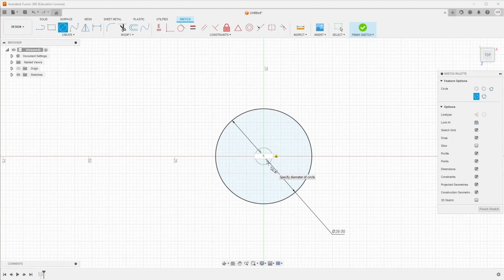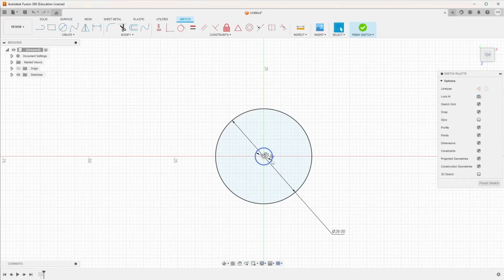Now, if you measured it and you were working in inches, you could type in something like 0.25 IN. And it will say, okay, well, I can put you in 0.25 of an inch or a quarter of an inch and do it in standard. But it is good practice to always stick with the same units of measure. So if you're going to use millimeters, just please use millimeters. And for our F1 in Schools, because the metric system is used in the F1 rules, that's what we're going to use here.